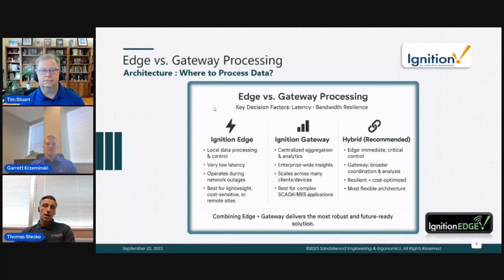So the benefit would be low latency, and we can continue to store data even in a network outage. And one real good thing about Edge is it offers polling close to the device. So we're not polling from a SCADA application. This can be on premise as a data collector, which can also publish data centrally once it's back online. So this adds IIoT to your SCADA system.